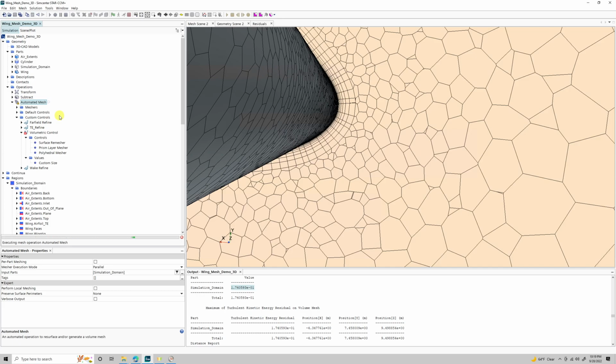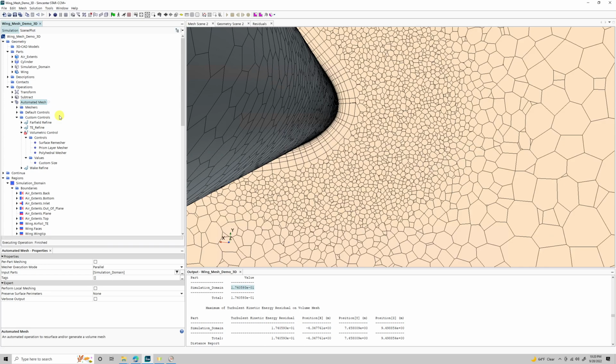Or it might be the opposite, where, hey, I reduced the maximum cell size by a factor of 2. Well, guess what? If most of your cells were at their maximum size, you just increased your cell count by a factor of almost 8. That could be bad.